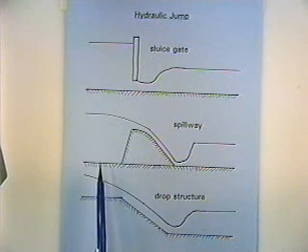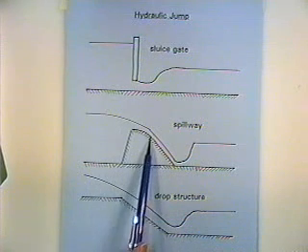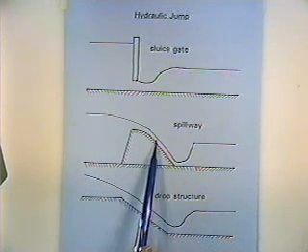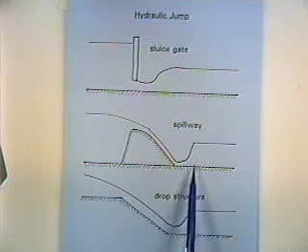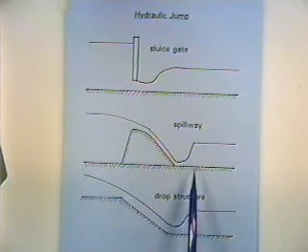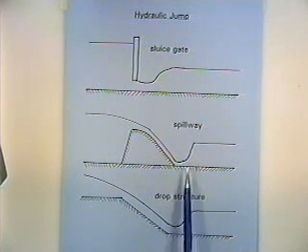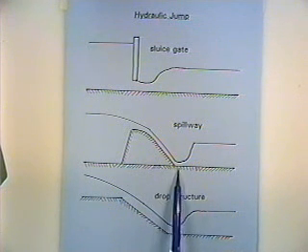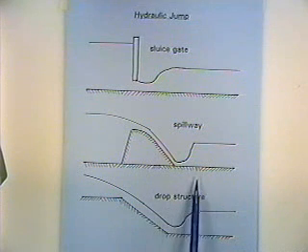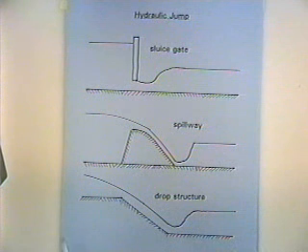Spillways allow water to flow over a dam without damaging the dam itself. And you get water barreling down a very steep concrete spillway. When it gets to the bottom, it hits a flat slope, and there's lots of energy dissipation. And we want that to happen because we want to have all the energy dissipation in some sort of an energy dissipation structure, like a concrete stilling basin, before we let the water go to the natural river. Otherwise it would erode away down to bedrock.